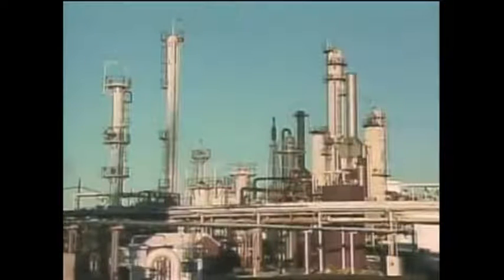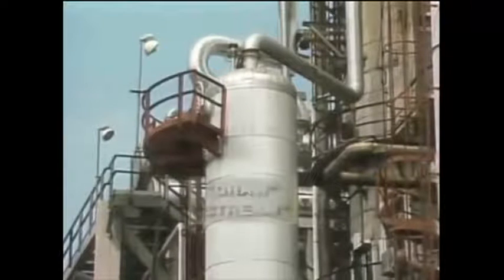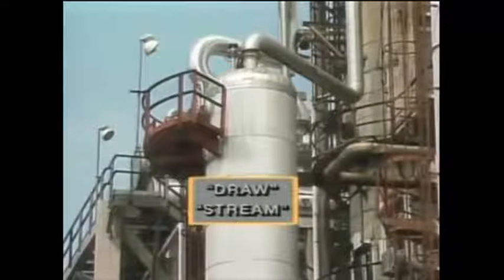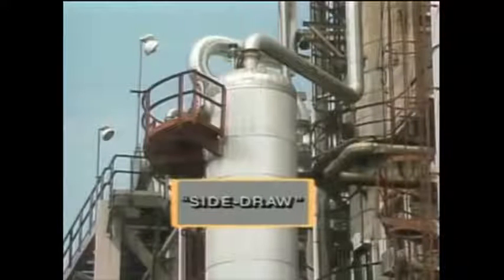Multi-draw towers are also referred to as side-draw towers because some of the products or draws are taken from the side of the tower. For example, one type of multi-draw tower has three draws, one at the top, one at the bottom, and one near the middle. Because a draw or cut is taken out of the middle of this tower, this type of tower is sometimes referred to as a heart-cut tower. Multi-draw towers can also have more than three draws to separate several products from a feed.